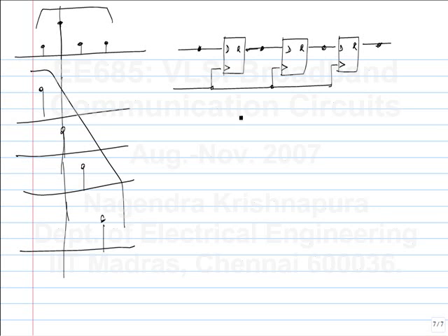So to ensure that it works properly, we don't use 3 flip-flops, but we use 4. Now the timing on this is not constrained. It can be anything, subject to the constraint that the flip-flop itself works properly. Now we have these 4 signals, which are 1 clock cycle apart. That is 1 TS apart. We use 4 flip-flops so that the timing is accurate.